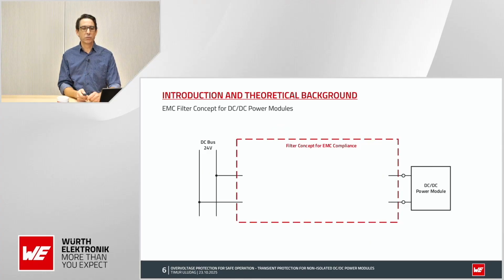So, to protect the DC-DC power module from transients, we need something in between where the voltage comes from and where the voltage is needed. This is here the area we are playing in today. This is then the EMC filter concept that is shown here in red.